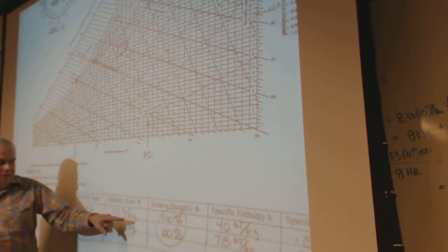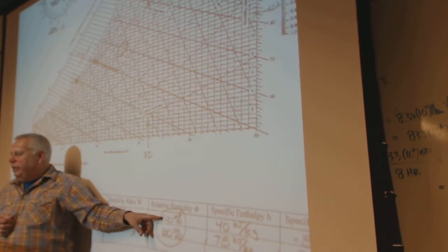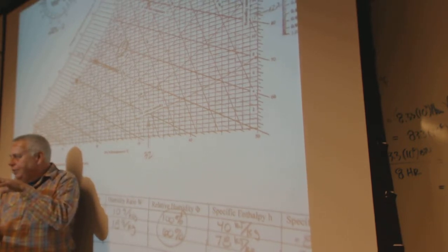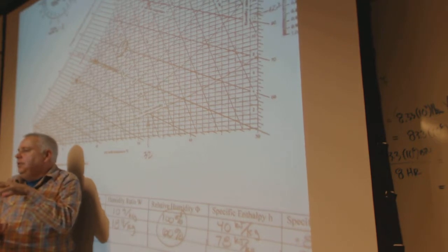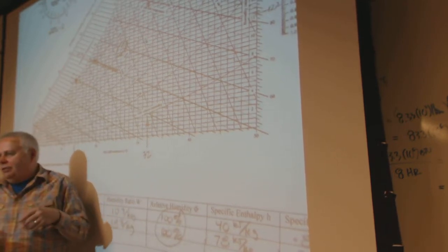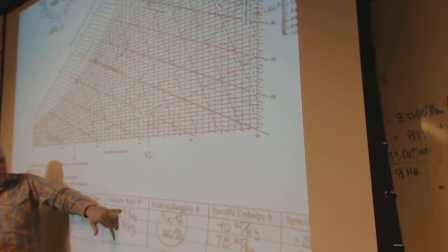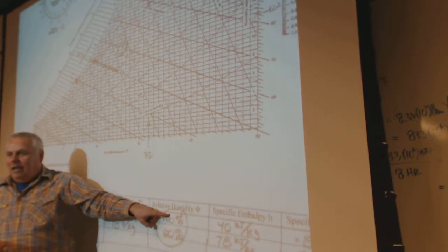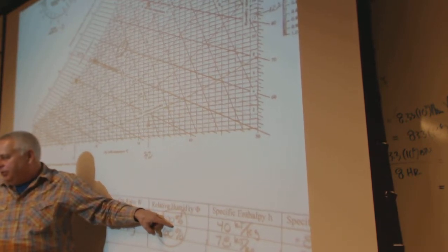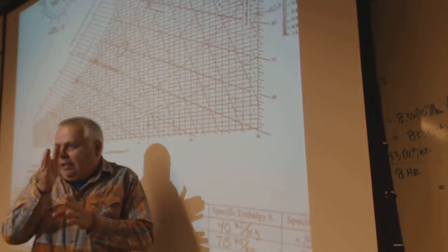But when you find that point, you find the humidity ratio is about water mass. It's a mass ratio. This is a pressure ratio: the partial pressure of the water relative to the saturation pressure at that temperature, what would be the boiling pressure, essentially, if you had it in vacuum. So this is a pressure ratio, this is a mass ratio. They're both ratios. But this is grams of water for each kilogram of air. This is the partial pressure of the water vapor relative to the saturation pressure for water vapor at that temperature. That would be on your steam table, same number. Just the steam tables are kind of crude when you're only talking one degree at a time.